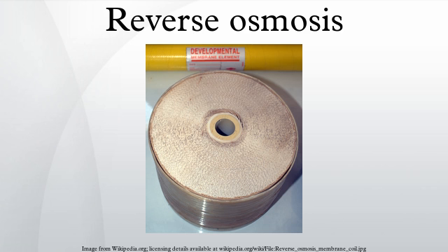In most cases, the membrane is designed to allow only water to pass through this dense layer, while preventing the passage of solutes. This process requires that a high pressure be exerted on the high concentration side of the membrane, usually 2 to 17 bar for fresh and brackish water, and 40 to 82 bar for seawater, which has around 27 bar natural osmotic pressure that must be overcome. This process is best known for its use in desalination, but since the early 1970s, it has also been used to purify fresh water for medical, industrial, and domestic applications.